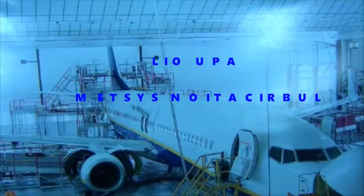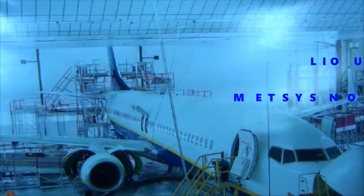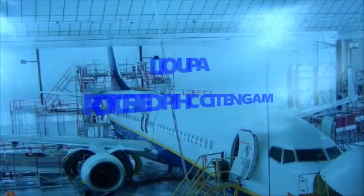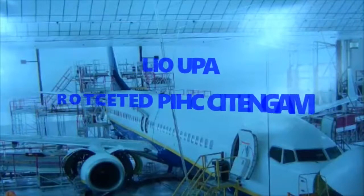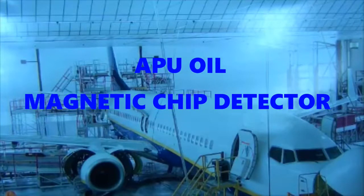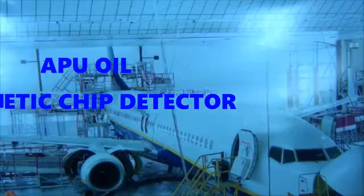Okay. And of course, you have that magnetic chip detector, just like you have in all oil systems, because you don't want those metal particles in the oil that'll damage components along the way. So the whole idea with the detector is being able to capture those particles. That's actually located on the lower front face of the gearbox assembly. And of course you have a drain plug along with that.